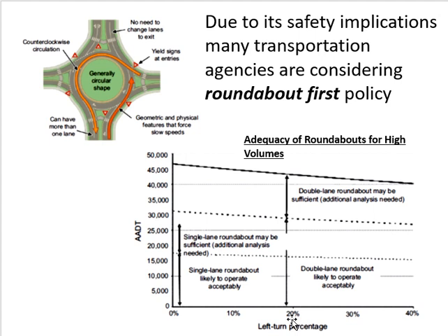So let's say your AADT is 25,000. So 25,000 is here, and let's say your percentage left turning is 10%. So 25,000 and 10%, a single lane roundabout is enough for you. Above this line, double lane roundabout. On this side of the arrow, double lane roundabout. So this whole portion is double lane. Above this curve is double lane, and only this portion is single lane. And you can check this, like I told you, this is a shortcut method, but you can look for more detailed methods in the books as well.